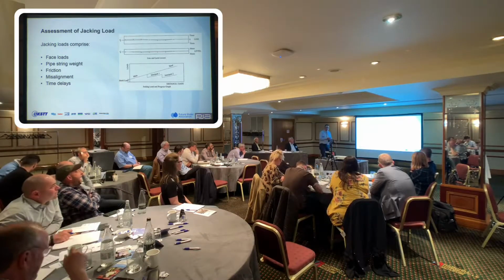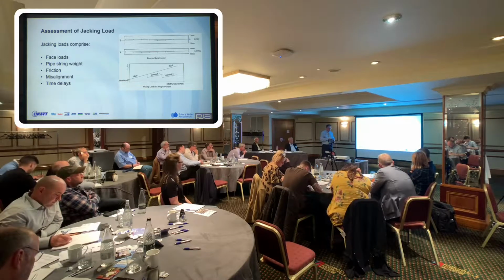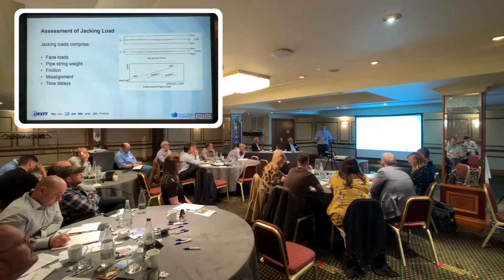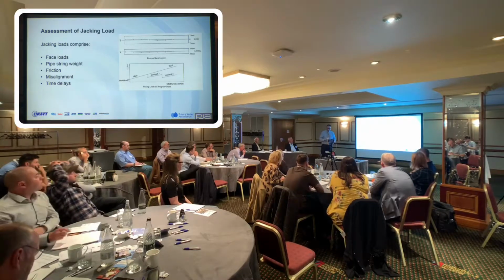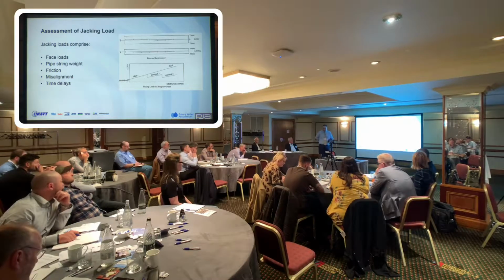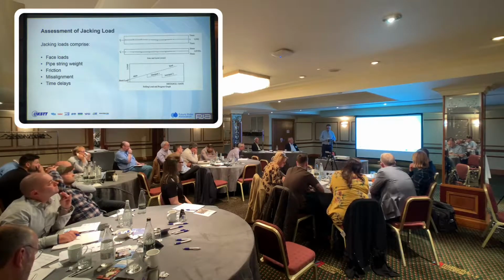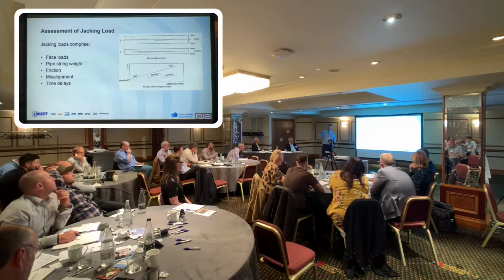Time delays. I suppose this is linked in a way to friction, but the whole idea of the pipe jack is that you're creating this hole and you put in the TBM and then you put in the pipe string through there. Now, if we take a clay, because it's a good material to think about, you excavate that hole and there will be a stand-up time.